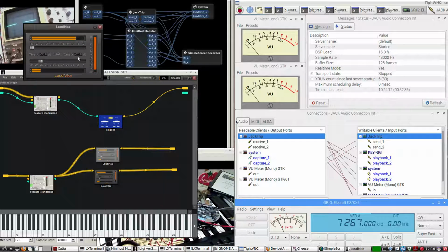And so this is adjustable, of course, but with a very steady volume, you want the least amount of ALC possible and still get full power. So I'm pretty stable at -25, and that's just about what it takes to get enough power. So I don't see any point right now in going over this, but if you needed more, you just look at your watt meter and then dial this up until it's just enough to get full power. Then that way you don't have to activate the ALC that much and you get less distortion.